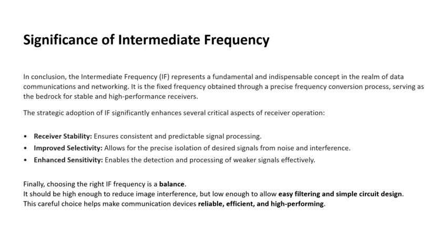What are the effects of the IF? If the IF is high, the image frequency moves far away, which is easier to remove using filters. If IF is low, the image frequency comes closer, which is difficult to filter. So, IF must be chosen carefully to avoid image interference.